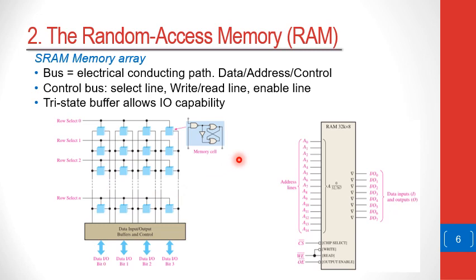As a RAM block, the array can have the following inputs and outputs. So it will have address lines, or typically what's called an address bus. Generally speaking, a bus here simply means an electrically conductive path. So whatever connects to this address bus, all of these 15 lines here will be called an address bus. And then there is also this output. It stores 8 bits each time. So this would be the data bus.